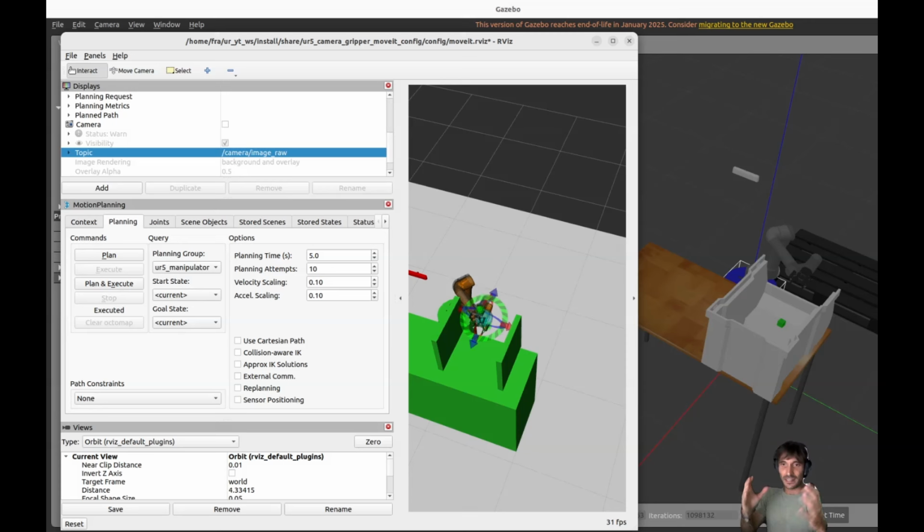So we have seen today that we have two manners. The first is letting MoveIt do everything. So let MoveIt read the sensors 3D YAML file that you have set up in the MoveIt configuration package, in such a way that MoveIt is taking the data that the camera is publishing, and it calculates its own Octomap.